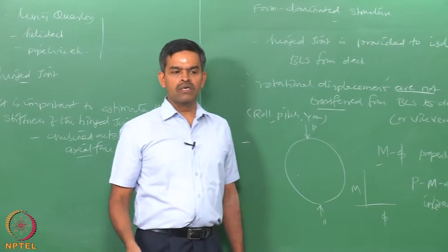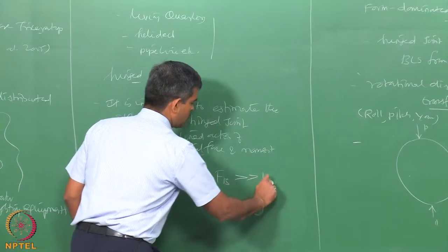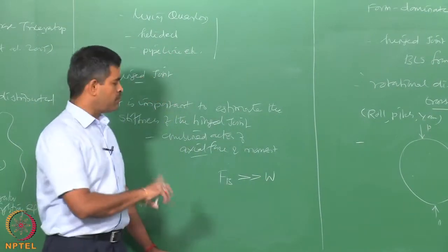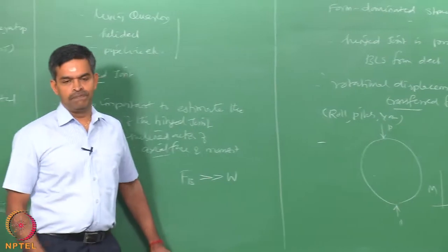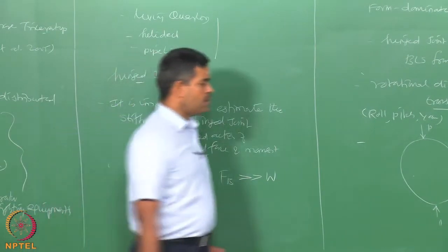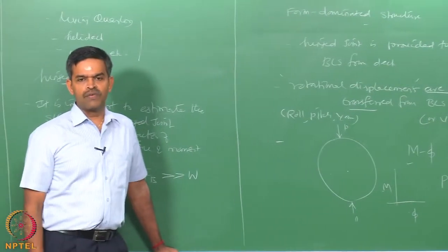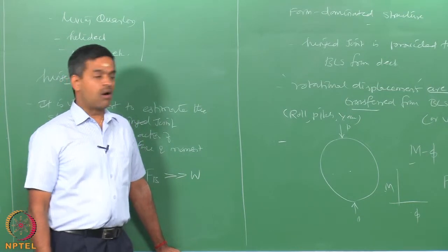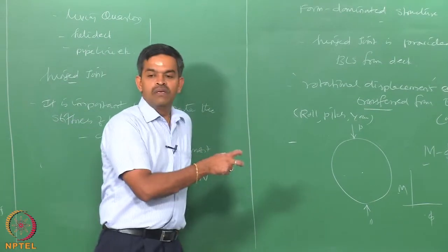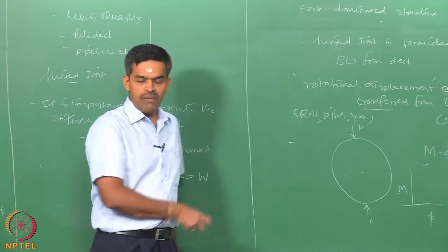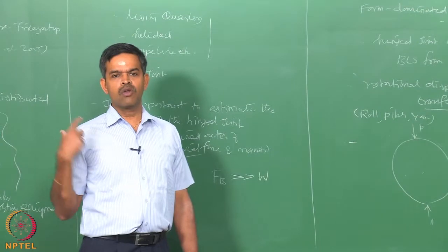Obviously, you can understand now that Triceratops is a positive buoyant system, where the buoyancy force very much exceeds the weight. Therefore, to commission this platform and to apply the weight on the system, you need to install the system on the sea bed. So, it is very important that the moment phi characteristics of the joint can be estimated only under the installed condition of a scaled model. So, the experimental modeling or the mechanical modeling in this case becomes very important to estimate one of the important variables in the reliability analysis, because this is going to tell me the survival safety of the platform under the given lateral loads, which is nothing but the reliability lookout of the whole system.